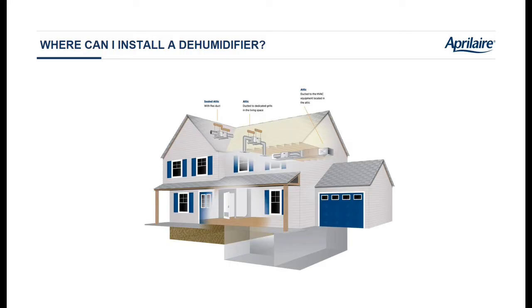When you seal up your attic space, so you spray foam it, you close up all the vents as a way to reduce solar gain, what happens is that stack effect still happens, but now you've sealed up that space, so there's nowhere for that moisture to go. So it accumulates in the attic. And if you don't address that, you can have a very significant mold problem in that attic. So a lot of companies are putting dehumidifiers in the attic just to dehumidify the attic to address that concern.